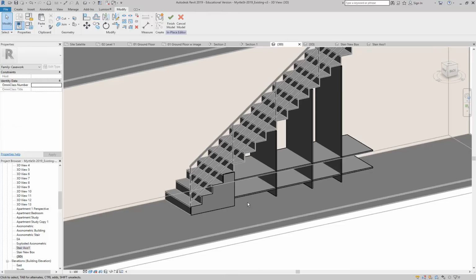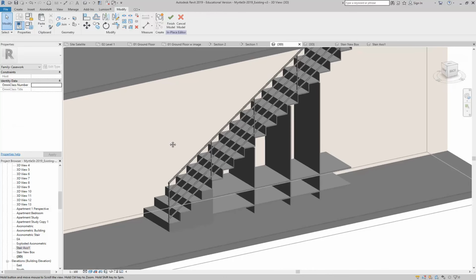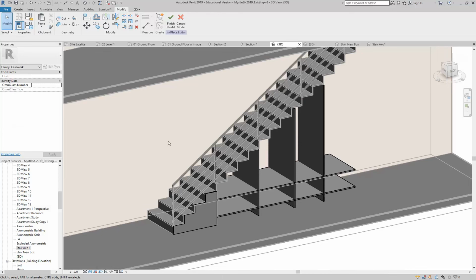So, yeah, that could be really good in the end. And yeah, you can do beautiful things just with extrusions because nearly every joinery piece in the world is made from flat board. Even the curved stuff. I know, I used to make this for a living. They get flat pieces of board and they cut notches in the back and they bend it around the frame that's made of flat bits. So it's all flat, which means the extrusion tool will let you make nearly everything in joinery and cabinet pieces. So that's all there is to it.